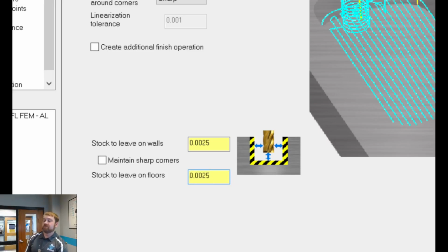The depth and the size of the pocket is important because it's what locates the part. We need to hit these numbers. I get asked a lot, with a pocket like this, how do we really measure that? Well, hopefully, before you go cutting your soft jaw pockets, you've already cut side 1 and got it on size. How many here have used a go, no-go before? Does everybody know the concept? It either goes or it doesn't go. When it won't go, we're not there yet. And once it goes, we're there.